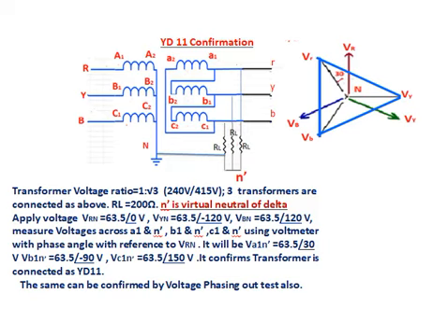But at site, we didn't connect RL and we want to form the virtual neutral point. So A1, that is LV side, A1 and N we shorted and apply voltage in HV side and measure the voltage between RN, R1, RY like that.